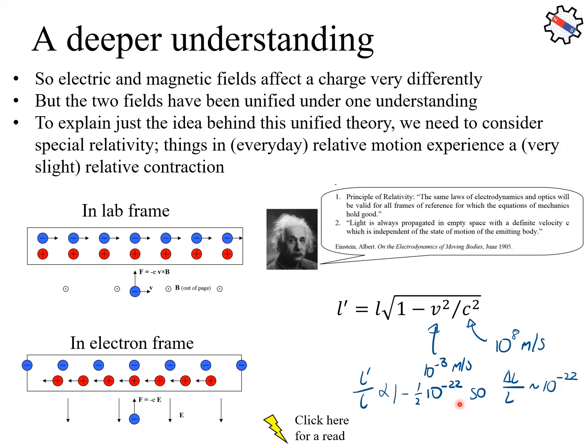Well, if you just think back to theme 2, we were saying a Coulomb charge is enough to lift the most laden oil tanker where it's 1 meter away from its opposite charge. Tremendous forces for any imbalance in charge. And if you consider the density of charges in a metal, free carriers, roughly 10 to the 23 a mole, right? And a mole of metal is only going to be 50 grams of it or so. So it doesn't take much length of wire before you have an awful lot of electrons contributing to a force when you consider a slight imbalance in charges in that volume.